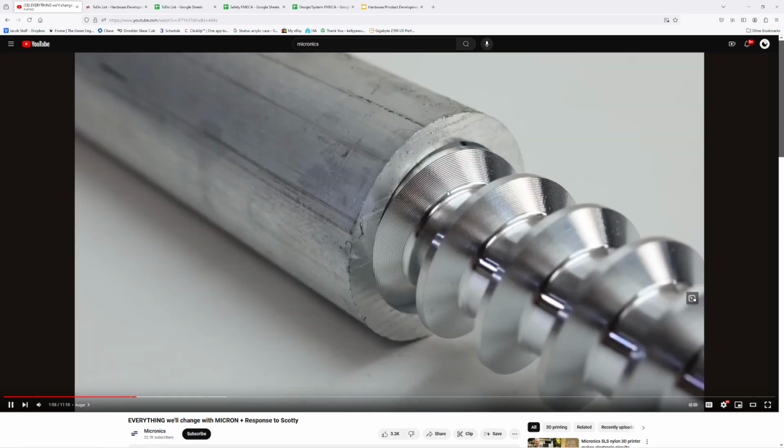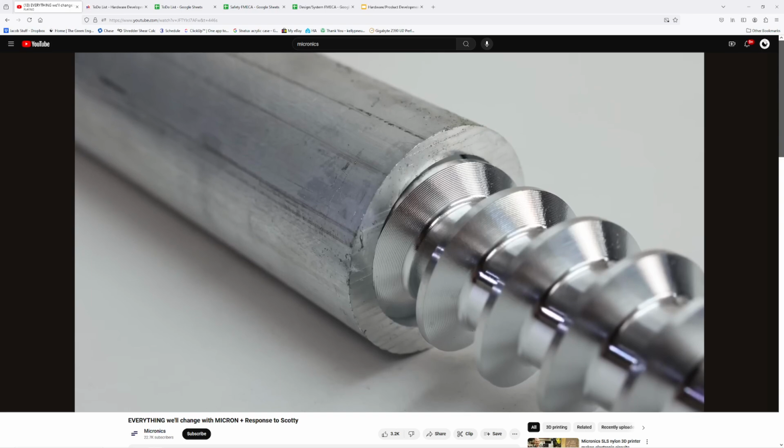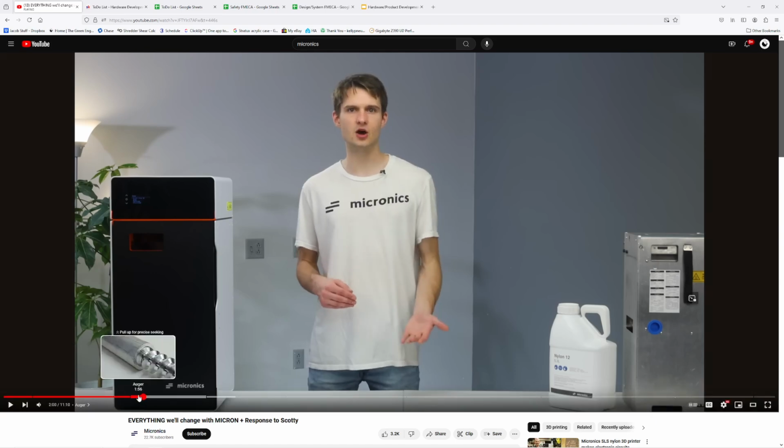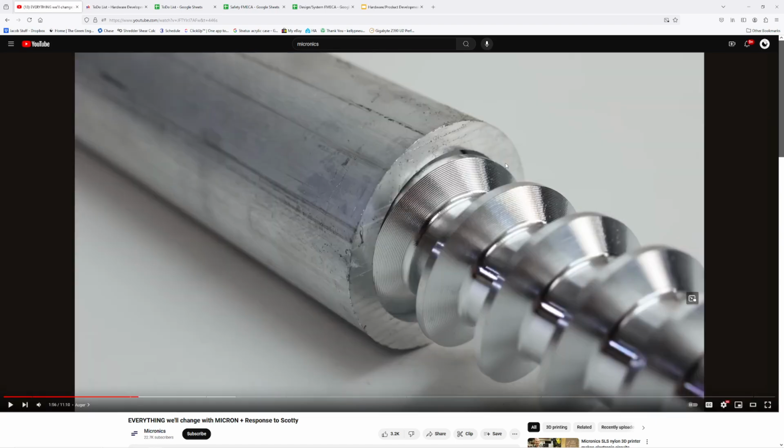Starting with the auger. Basically, it all comes down to clearance. Early on, we had issues with powder leaking back down the... This looks like a very, very cheap built-to-print part. It's not even outside surfaced. Like, how's your tolerances here? I guess it doesn't matter. It depends on your clamping. It's also your machining here. Looks very, very rough, right? I don't know if they made this one in-house. We have a lot of chatter here, right? And this surface step over finish is not very good. So it looks like this was maybe done on a mill with a 4th axis.